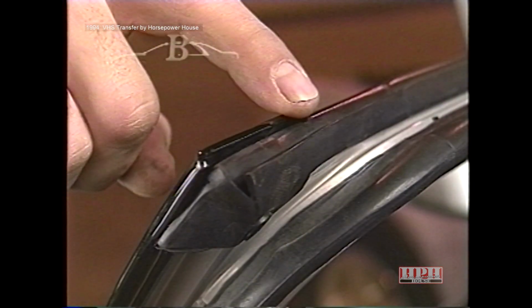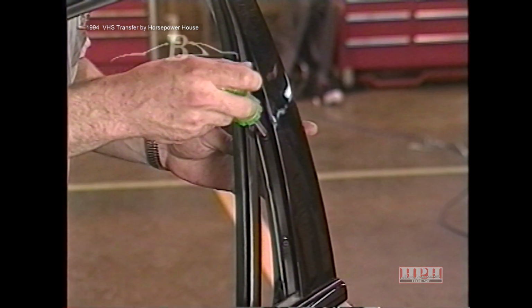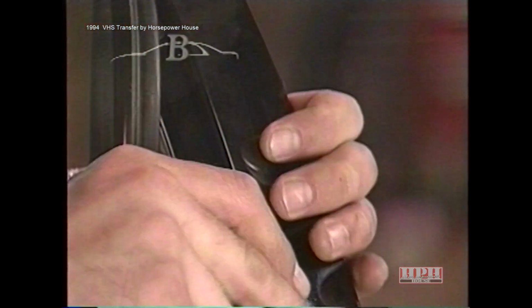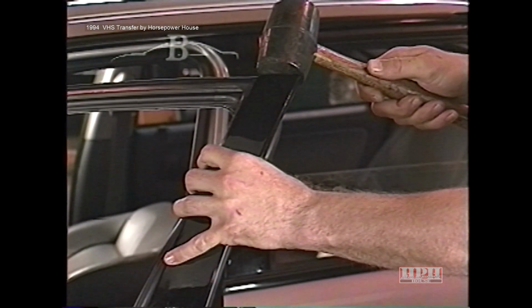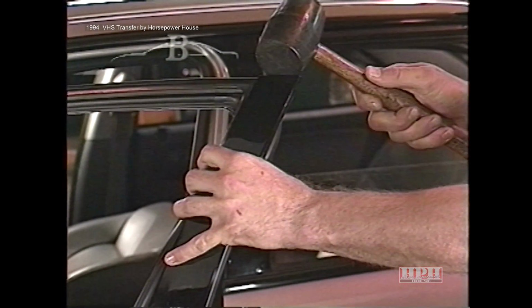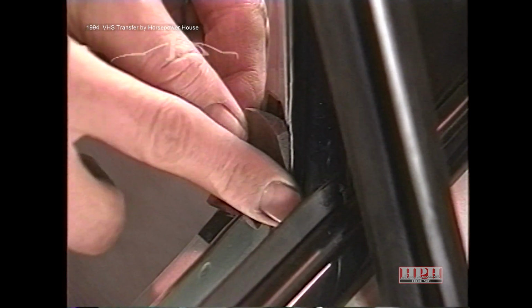Traffic noise at the B pillar can be the result of a poorly aligned B pillar applique. To eliminate the noise, loosen the applique screws and adjust to fit the door. If a gap still exists between the applique and the weather strip, the door can be tapped with a rubber hammer until flush. An opening between the inner belt reinforcement and the inner panel could allow traffic noise into the car. Cover this with foam tape.